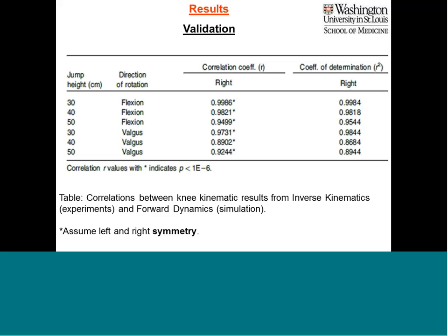So from there, I'm going to move on to our validation. As I mentioned, that validation was performed with forward dynamic simulation, where we use the muscle forces from computed muscle control to actually activate forward kinematics. So we compared the angles from forward dynamics, which is the knee angles, of course, between forward dynamics and inverse kinematics, and we saw very good correlation between these angles.